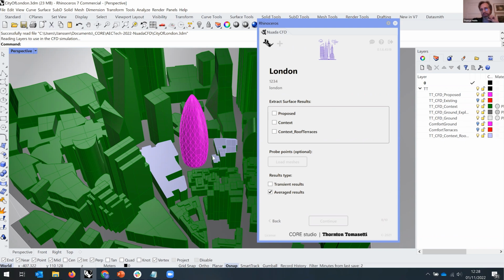And the typical mesh cell size for the analysis, how big is that? Well, to be honest, if I would turn this probe on and get results on that building, that's very fine actually. SimScale goes really into the single centimeters. So often much finer than you need. So I would recommend using this load mesh option, so that you can control in your Grasshopper script, for instance, where you want results from, where you want to measure the UTCI.